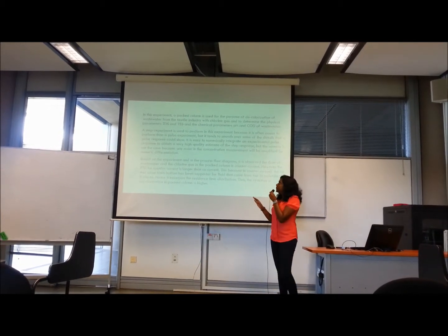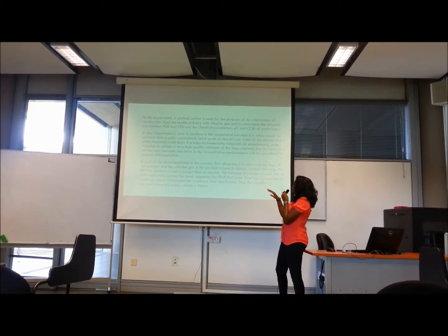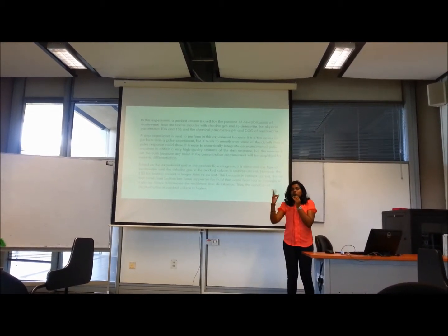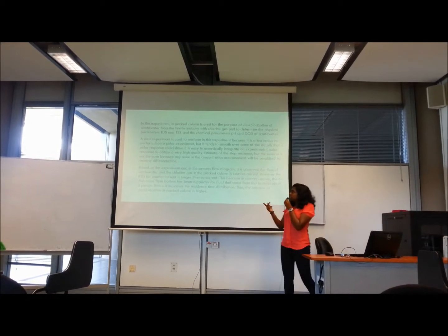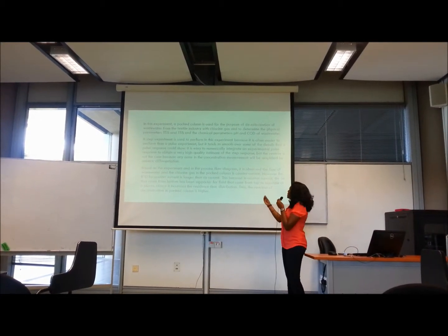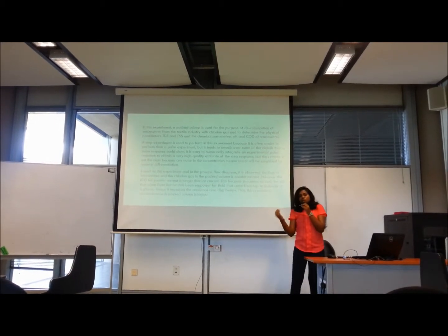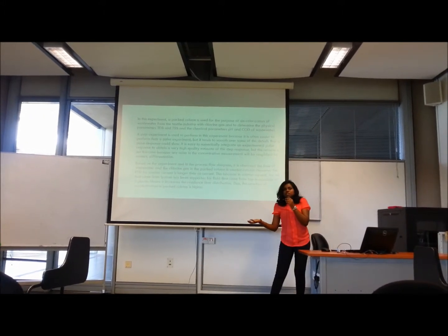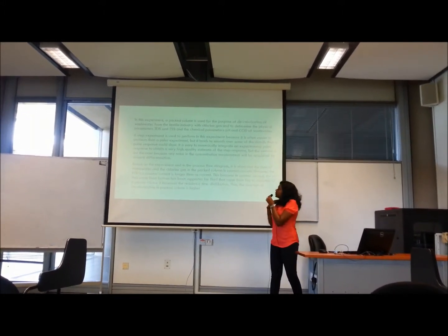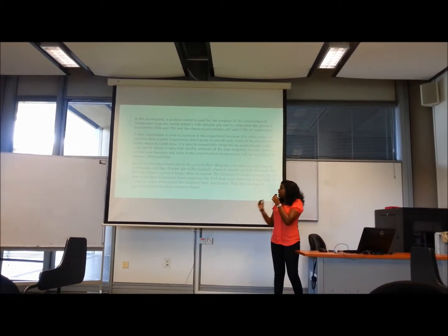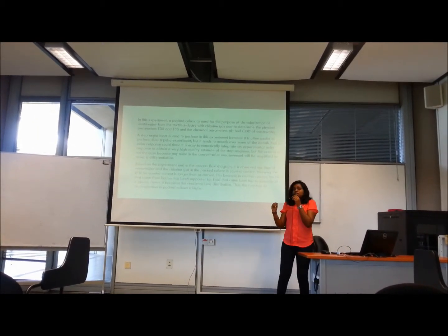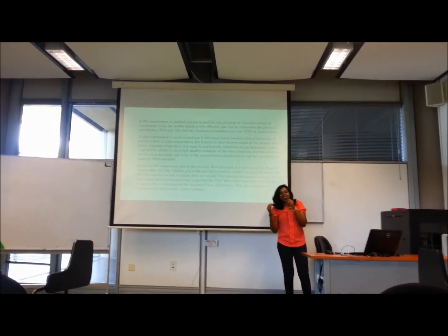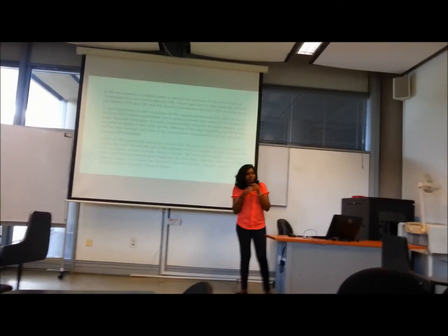Based on the experiment setup, it is observed that the flow of wastewater and the chlorine gas is counter current. The RTD for counter current is longer than co-current. This is because in counter current, the chlorine gas is supported by the fluid that comes from the top and is maintained in place. Hence, it increases the RTD. Thus, the decolorization reaction happening in the packed column is also higher.